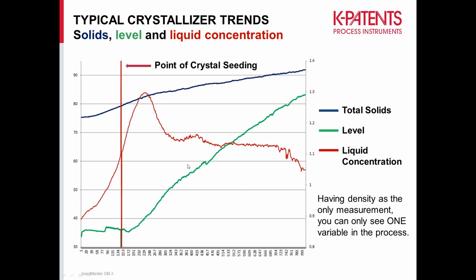And as the seeding process begins, you can look at the supersaturation, which is shown on this right-hand side, and the optimum level is between this 1.1 and 1.2 ratio for supersaturation. So you can see what's happening in the liquid stages, so you continue to feed that concentrated liquor to the same supersaturation state, and then you'll get fine crystals and conglomerates. It's a very good application for crystallization applications, and it's very necessary to have both your density as well as refractive index.